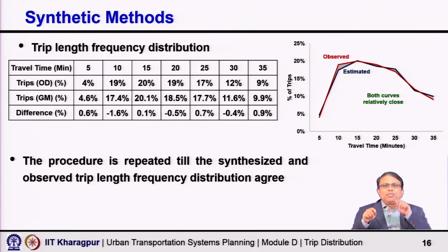Then you consider 5 minutes, 15 minutes, 25 minutes, like that up to whatever is the upper range you consider, and then you follow the same thing, taking the midpoint. But once you get the curve, even for any intermediate value, if I have 8 minutes, what is my friction factor value? I can get it from the curve you have established.